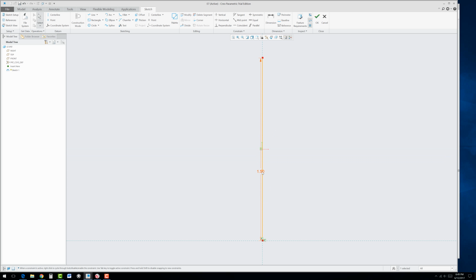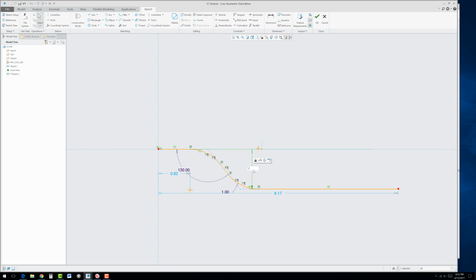The next dimensions we're going to put are the fillets. So go to the fillet and click here and here and there and there. Middle click a couple times, change them both to 1 if you like, or use an equal constraint. Select both geometries, and now they become equal. It might have weakened this dimension. Let's go ahead and fix that. Just drag that out again, change it to 1. Okay, go to dimension and select this line right here. Drag it down, middle click, and let's just verify the manual here. That's going to be 2.25.